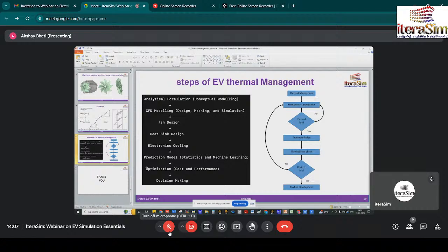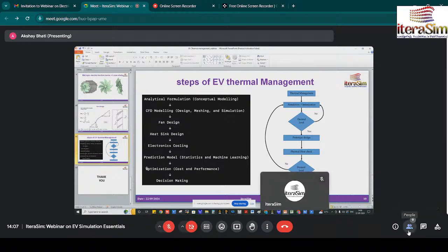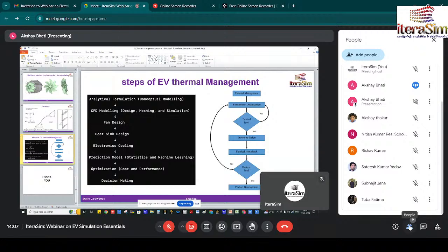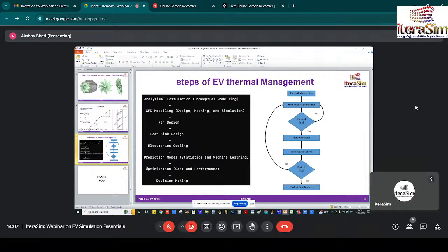External fans means fans which have an external power supply that would come from the battery or another electrical medium. So what they do is use a shaft-mounted fan, in which the fan is installed on the e-rickshaw motor shaft. As the e-rickshaw moves, the fan also moves, so it will suck the air and throw it on the casing of the motor. No external agent is required, otherwise the efficiency will decrease, because it's a lower power rating application.